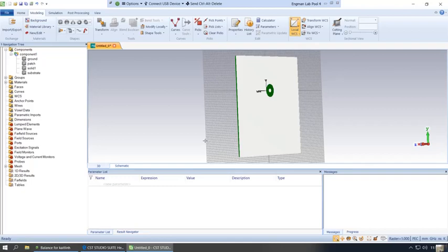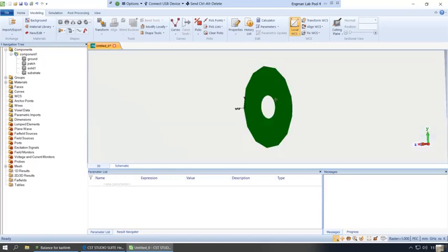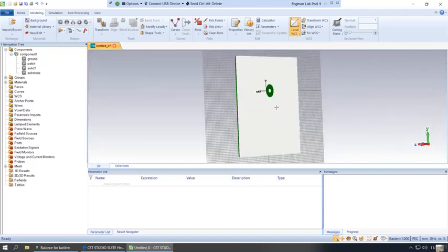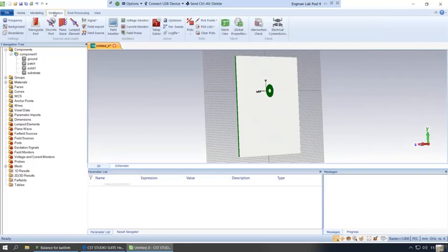So the next step is to set up the simulation. And so the first thing we need to do is create what is called an excitation port. And so this is a way of defining, here is how the excitation is going to come in. So remember I said that imagine we had like an SMA connector that would connect a coaxial cable into this antenna, and that's what's bringing a signal from our, say, electromagnetic generator. And so the way we model that from a simulation point of view is by creating what's called a waveguide port. So we'll go to simulation, waveguide port.